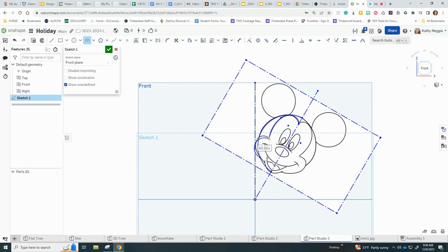Okay, I'm also going to choose from the center line to here, bring it out a little bit for the mouth. And it might be easier to make this part of the mouth with just the line tool. So I'm going to use that, bring it in, escape. Okay, I have some more 3-point arcs I need to create. So I'm going to create that.